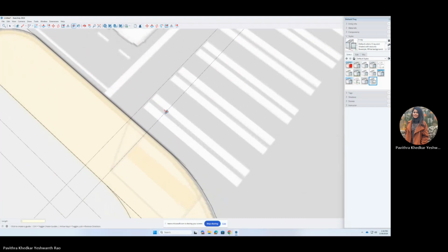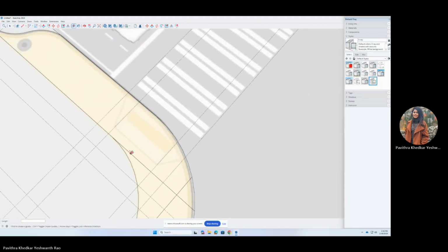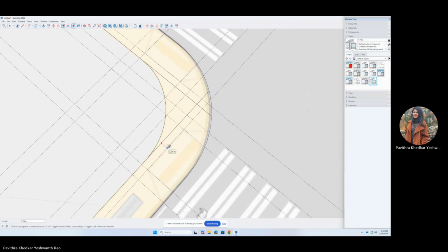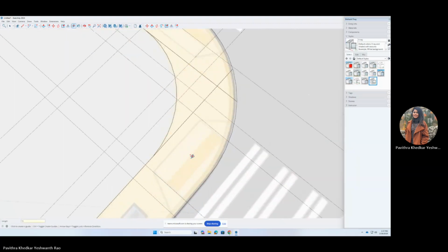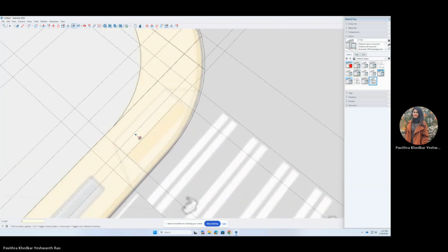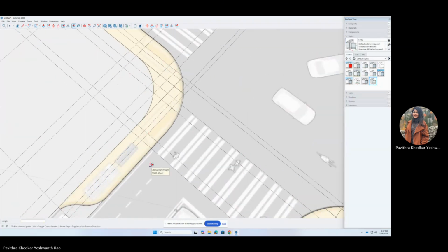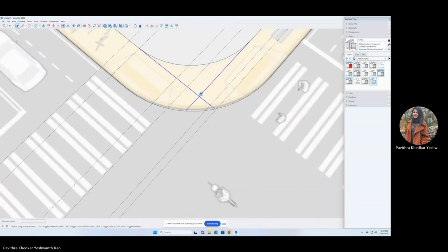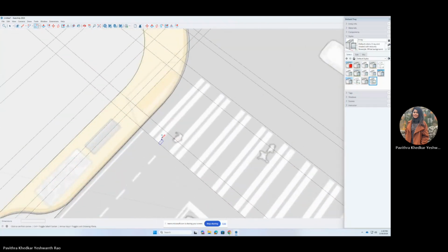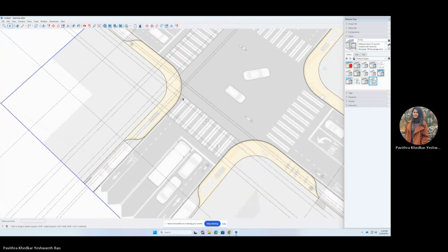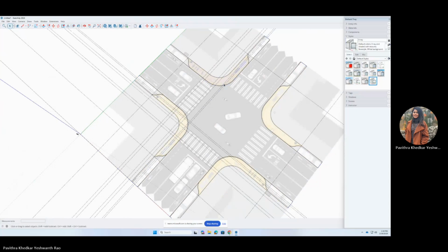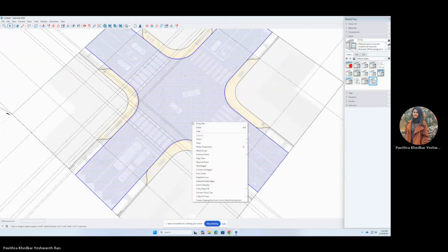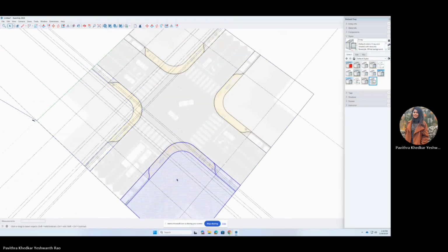Avoid drawing directly on grouped objects. Always enter the group before making edits to prevent affecting the other geometry. This method allows you to edit individual components without disrupting neighboring components and elements. Regularly check for unwanted gaps and overlapping lines that could interfere with the model and precision. Once your traced model is structured and grouped correctly, you are ready to move into detailed 3D modeling.